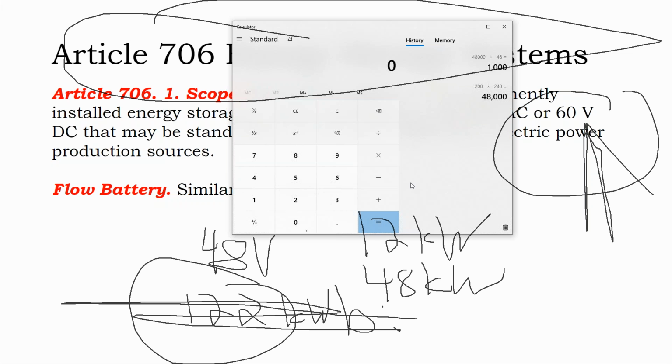That's parallel runs of incredibly thick battery cable. Now, you can find lead acid batteries rated for 1,000 amps output, but your battery cable sizes are getting into the size that you'd use for utility scale facilities. With incredibly high amperage, you're spending too much on your cable.